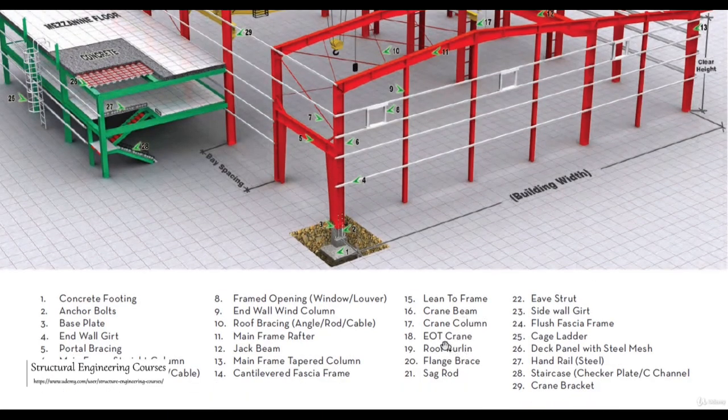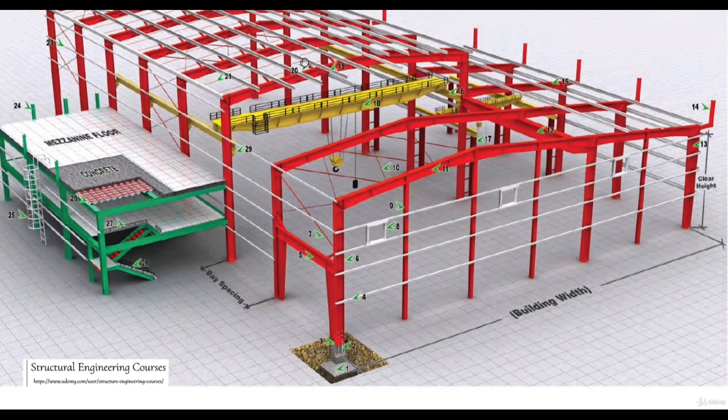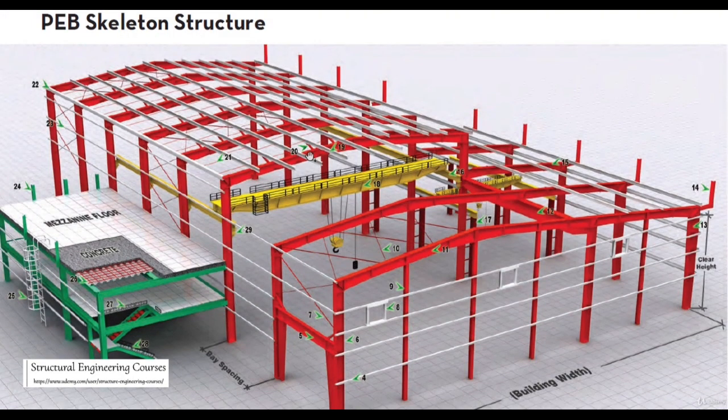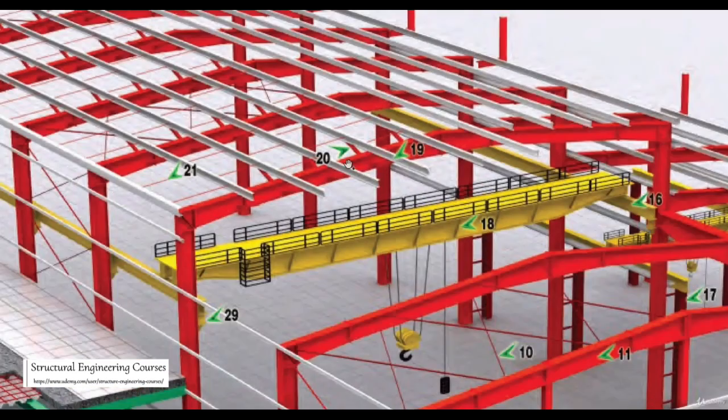After that, the roof purlins that I had already explained here, the purpose of these roof purlins is to support the sheeting arrangement on the top. Number 20 is the flange brace, that is this brace. Now this is also a very interesting concept, that is, why do we need to provide this flange brace here. These are mostly Z-shaped purlins here, and as an engineer, you know that the bending moment is directly proportional to the length of the member. I repeat, this is an important concept, that the bending moment that gets generated in a member is directly proportional to the length of the member. It can be either WL square by 8, or in purlins, as they are continuous, the bending moment is usually in the range of WL square by 10 to WL square by 12.